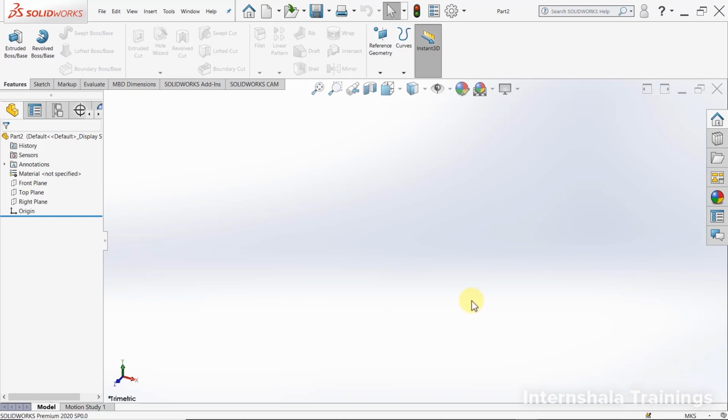However, naturally, I do not want to keep changing the unit system every time I start a file, because most likely I will be working on hundreds of them. So a better way would be to change the default unit system to mks. So when I open a new file, it will be on mks to start with. So let's see how we can change the default unit system, in my case, from mmgs to mks.